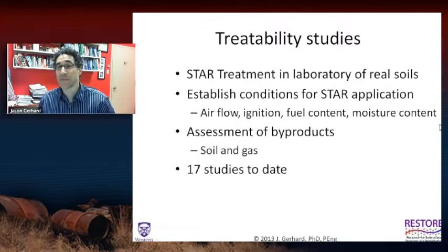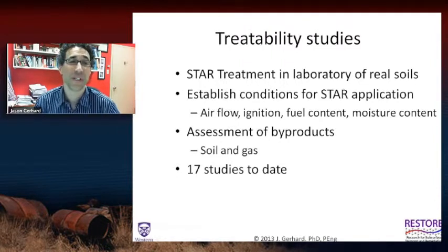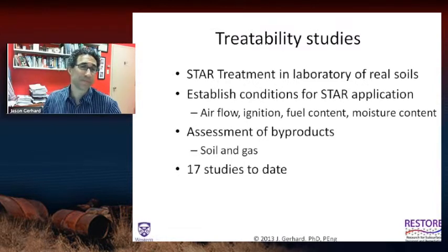So we're going to talk about treatability studies briefly. Pretty much any kind of remediation technology generally has a treatability study. That means you take contaminated soil from a real field site, send it to the location to do the treatability study, and they can tell you whether your contaminant, your soil from your site, is suitable for this kind of technology. So, of course, we've developed that for STAR, and it's available for bioremediation and for ISCO and for everything else.